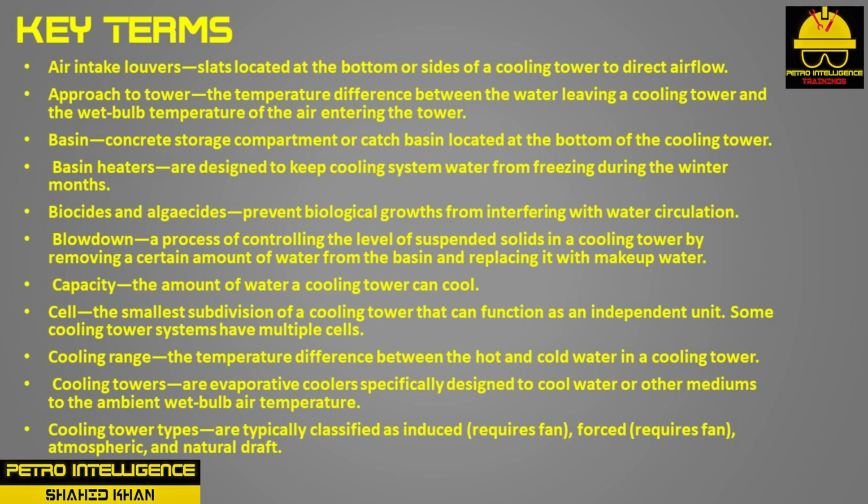Basin heaters are designed to keep cooling system water from freezing during the winter months. Biocides and algicides prevent biological growths from interfering with water circulation. Blowdown is a process of controlling the level of suspended solids in a cooling tower by removing a certain amount of water from the basin and replacing it with makeup water.